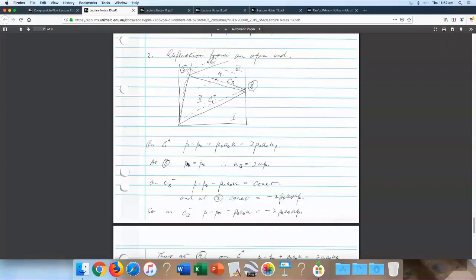You know, real engineering has real compromises here. I have a wing that has got to carry a bending moment, and maybe I've got to have a rounded leading edge. Maybe I can't make a sharp leading edge, or maybe I don't want a sharp leading edge because this aircraft's got to take off and land subsonically. So typically, it'll probably have a rounded leading edge. So that's for the subsonic flow? That's the subsonic flow, but then when the aircraft's flying supersonically, unless the wing is oblique to the flow,